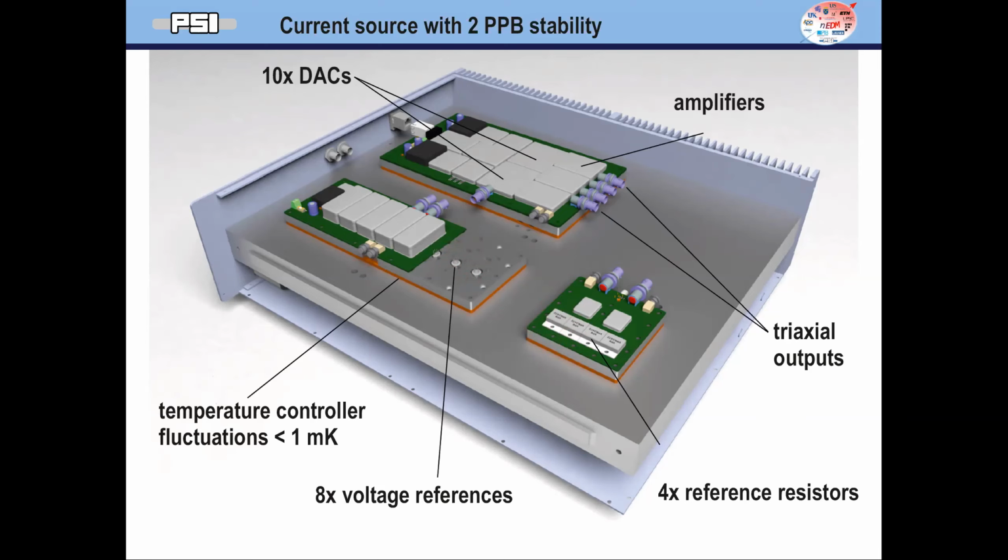And then using Ohm's law, you need an amplifier that drives the right signal to your coil such that the current that flows through the coil and then through the reference resistor, so those are in series, gives exactly the voltage value that you want. This is how you make a really, really stable current. And I've shown you with the ADC performance chart that there is a limit how well you can do that.